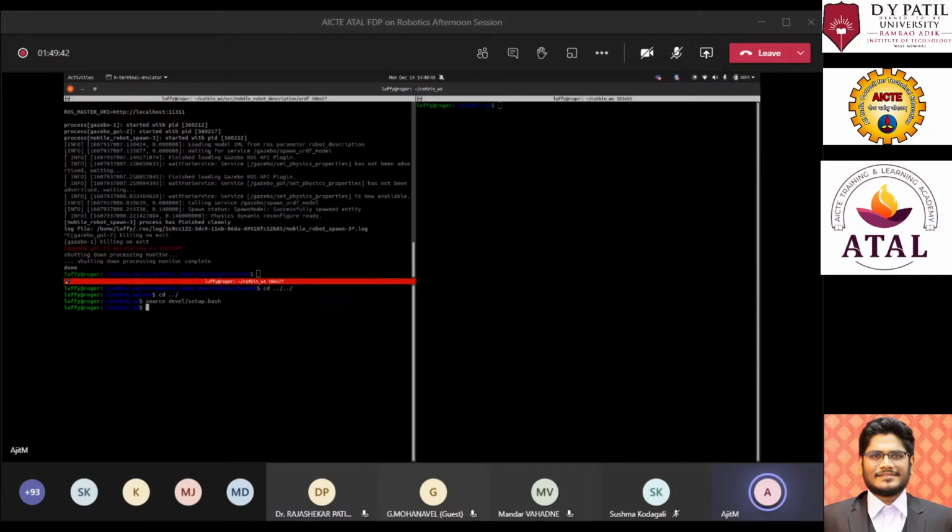No name. Oh, okay. So one thing which I have forgotten to mention to everyone is that in the robot tag, we have to give it a name. That name is given to this robot, which will be used by ROS in the parameter server. So what is the parameter server, you will say. Parameter servers are a bunch of parameters which are loaded once we start the simulation, and using these parameters, Gazebo and ROS do the simulation. So right now I'm naming this robot mobile robot.